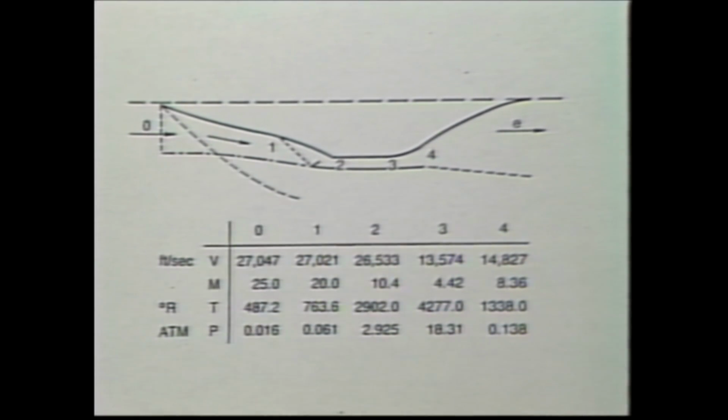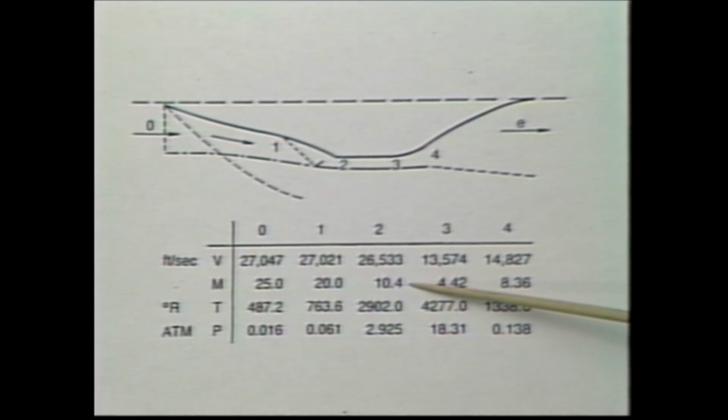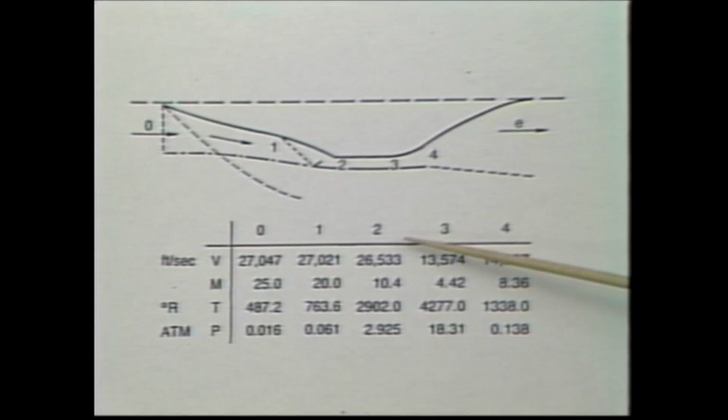Notice that across the shock, there isn't much of a velocity change. But notice also that the Mach number changes dramatically. That's one of the key features that we see in hypersonics. Under the flow conditions that something like a hypersonic vehicle will see, in general, changes in Mach number translate into changes in temperature, not in changes in velocity. That's very convenient, because it means that even though we might drop the Mach number in the engine down substantially from the flight Mach number, the velocity of the flow inside the engine is probably pretty close to the velocity outside the vehicle. That's a good rule of thumb.